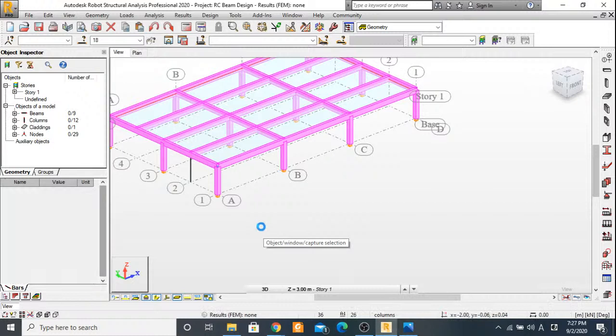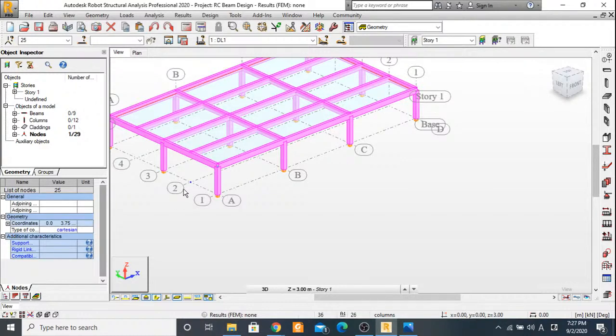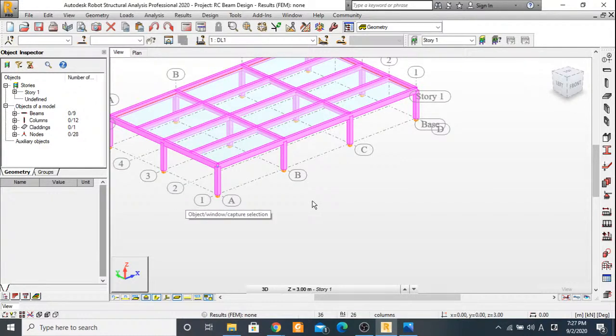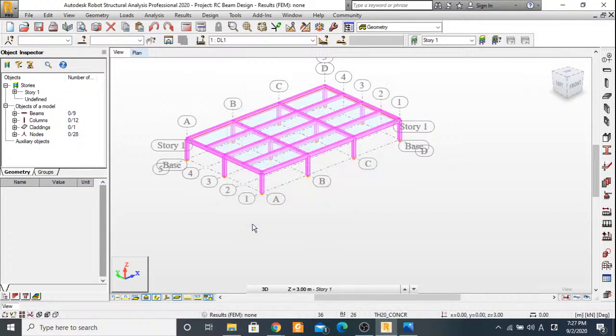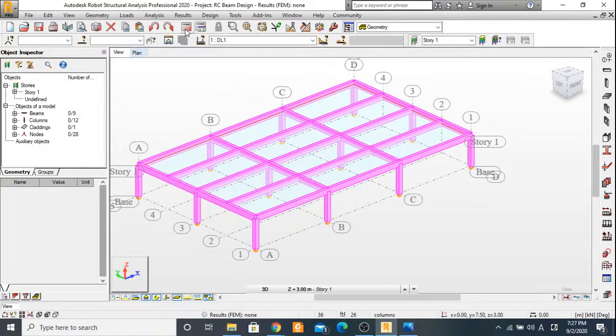All right, so let's just delete that. I hope it's leaving no node on the floor here, no isolated node. Let's just delete that too. Okay, so let's go again and do the load combination and see whether that was what was causing the problem. Yeah, nothing has changed at that level, right? So we'll click on load combination.